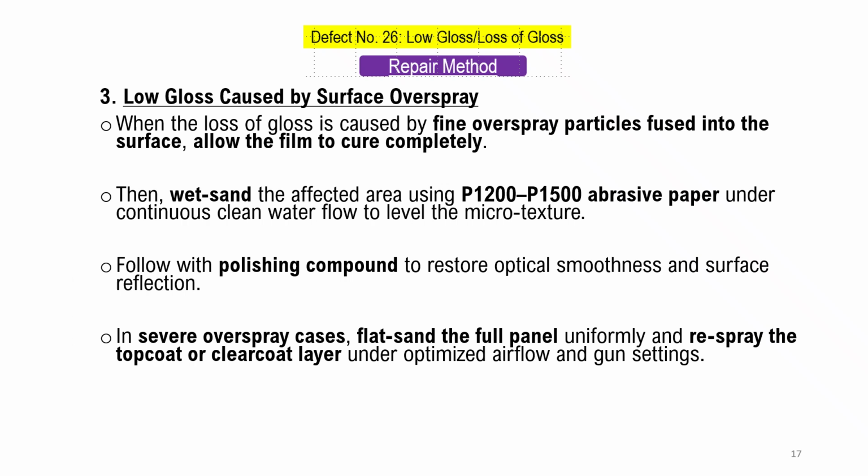In case of severe overspray, flat sand the full panel uniformly and respray the top coat or clear coat layer under optimized airflow and gun settings.